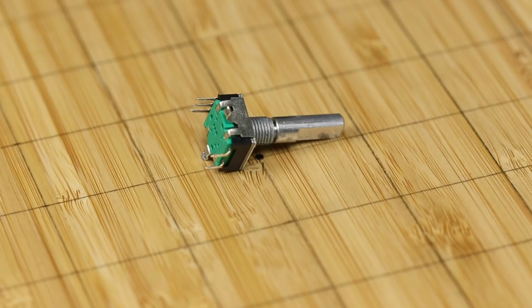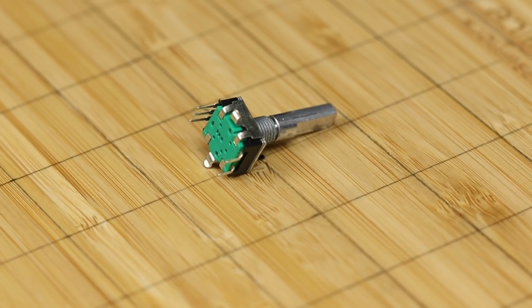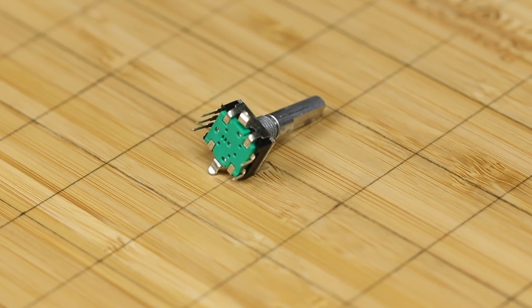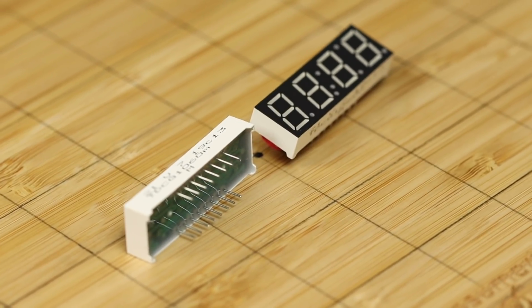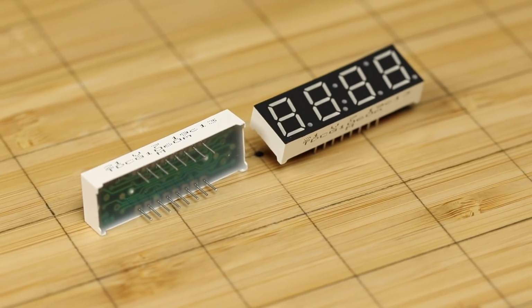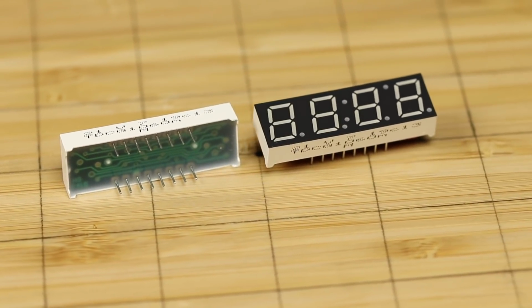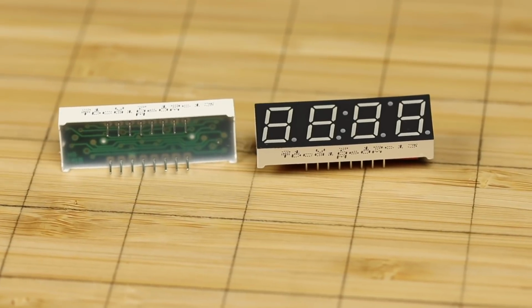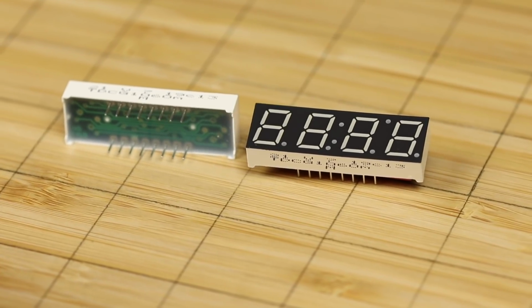For the encoder, I'm going to use the same good old Bourns encoder that I've used in a bunch of other projects. It's got a great feel, I know what libraries to use, and it's super easy to connect to an Arduino. I found these 4-digit 7-segment displays that have dots between the two centered digits on the display, which is perfect since we're going to be displaying time. They are common cathode and made by a company called Vishay. They're going to take a bunch of I/O pins, so I'll probably use a couple of MCP23017s to drive them. Awesome, we've got an idea, we've got all the parts, let's get it out onto a breadboard and get through some design and start building this thing.